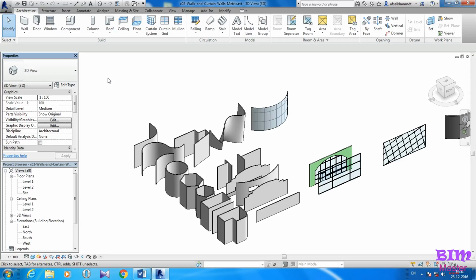Revit has 3 fundamental types of walls: basic, stacked, and curtain walls. Basic walls. The Revit Architecture default template includes several wall types. The most basic wall types have no detailed structure and are named with the prefix generic for easy identification. Other wall types have highly detailed structures known as layers. Each layer is assigned a function, material, and thickness.